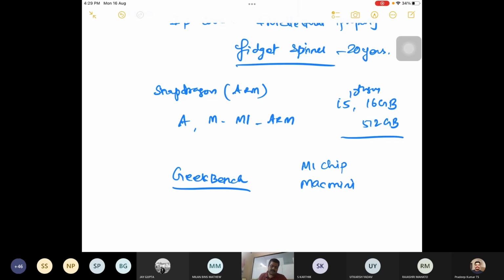Why I am telling you this is that we have two sections: one is the embedded system, and the other is the desktop system. The embedded system is what we call the CPS, cyber physical system, and the other is the desktop system. The desktop goes for a von Neumann architecture, while the embedded goes for a Harvard architecture. The data memory and the program memory are in two different logical spaces, but we still use the same clock frequency to access them. That's how we make the system steadily faster.